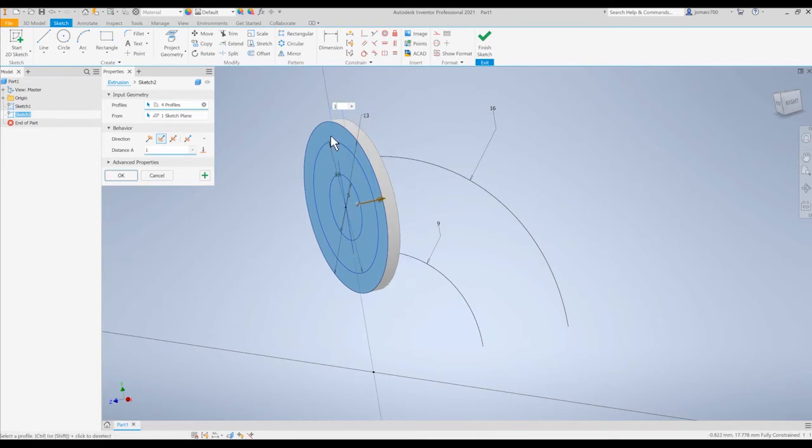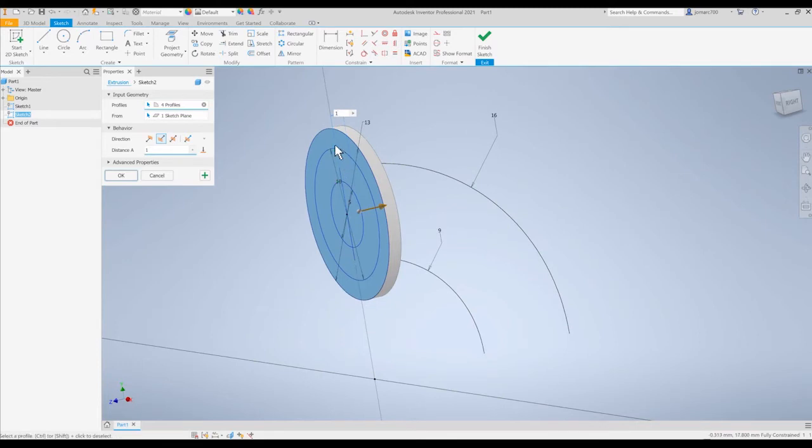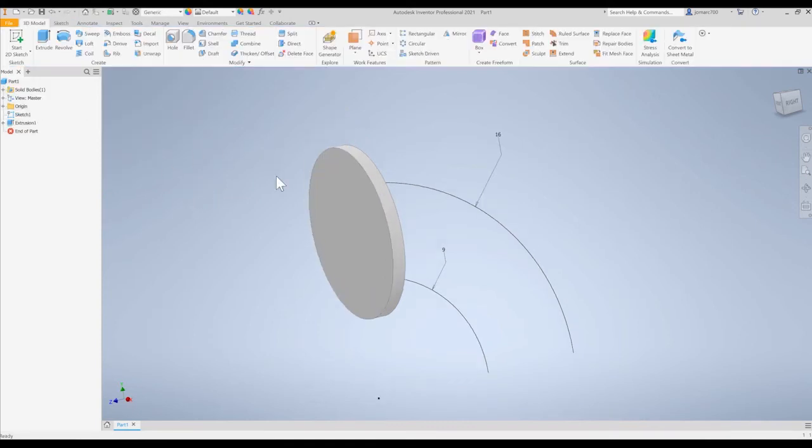Now we have the option to create the circle here so that when we create the extrusion, it will have a circle. But in this instance, I prefer to create the circle using another feature for us to have the option of creating circular patterns. So we're okay with this circular extrusion. Let me now select OK. Next, let's turn on the visibility of our previous sketch. So selecting Sketch 2, right click and select Visibility.